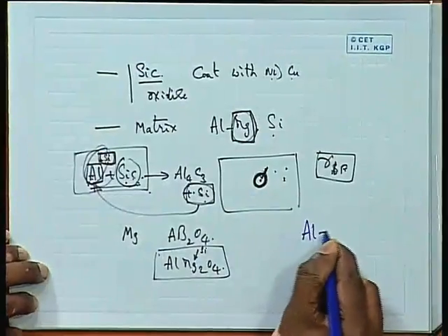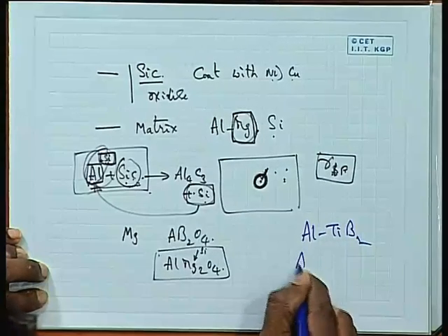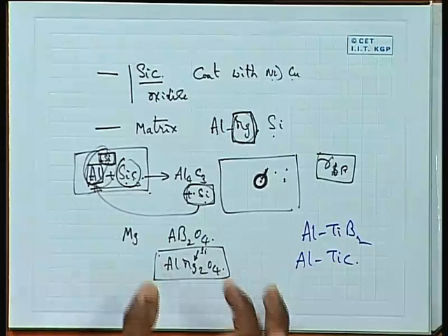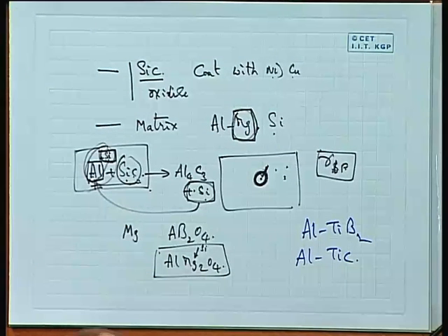So, because of this, aluminum silicon carbide composites are still being worked out by making these kinds of modifications of either the matrix or the reinforcement particles. But there is a lot of tendency to develop newer composites, which are called the new generation composites, and two examples of that are aluminum TiB2 and aluminum TiC. We will try to see some results of this work people have been doing in this particular direction.